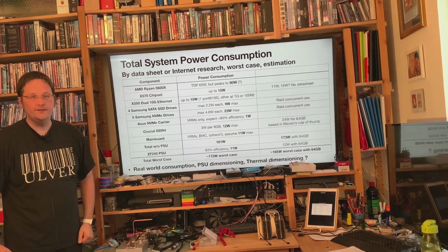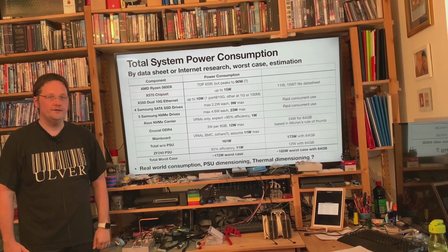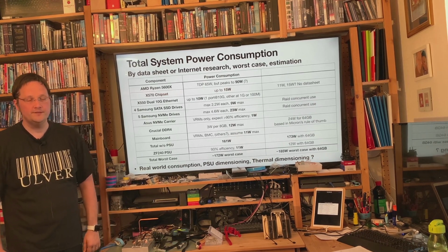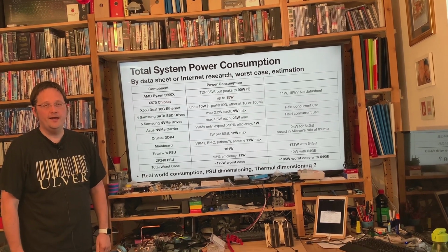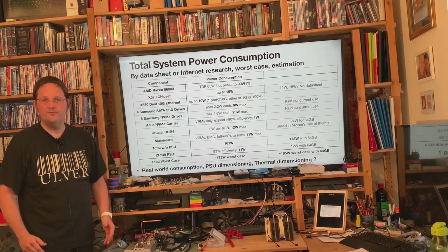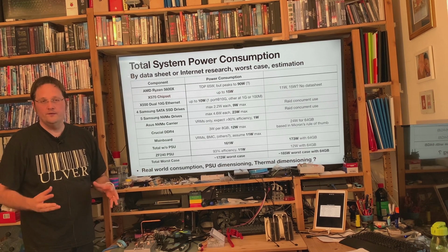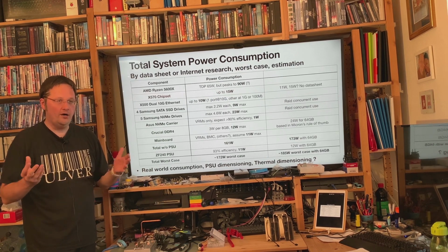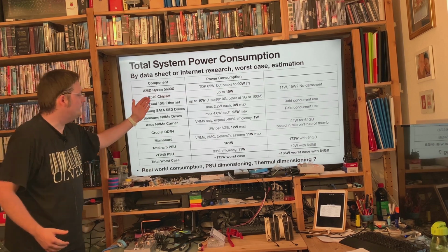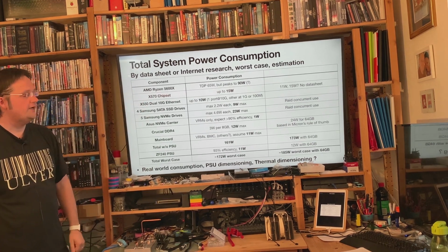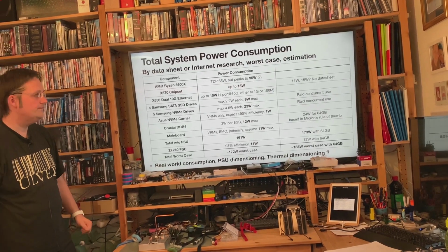The X570 chipset, I was not lucky to find a freely available datasheet for this. I found some people who did analysis on the power consumption of that chipset, and the number that was coming out there is somewhere between 10 and 15 watts. So I was not able to really find a hard number, just a span. So I will just say, okay, for the X570 chipset, we are going to calculate with up to 15 watts.